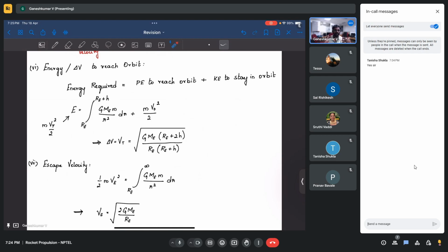And then the rocket will have a nozzle, chamber, tanks and all those things. If I want to achieve this much thrust and this much Isp, then I need to do something with the nozzle, something with the combustion chamber, and something with the tanks. If it's a liquid propellant, I need to do it with that. If it is solid propellant, then I need to do some optimization in that. So you see, this is the structure of this course. This is how it has been designed.